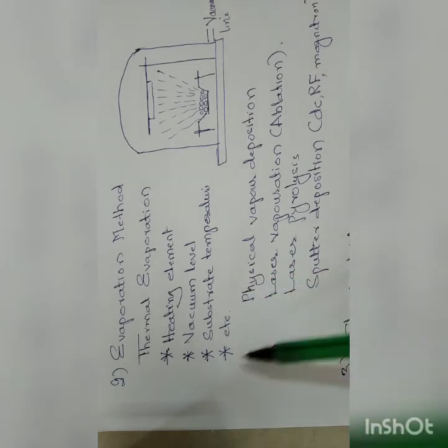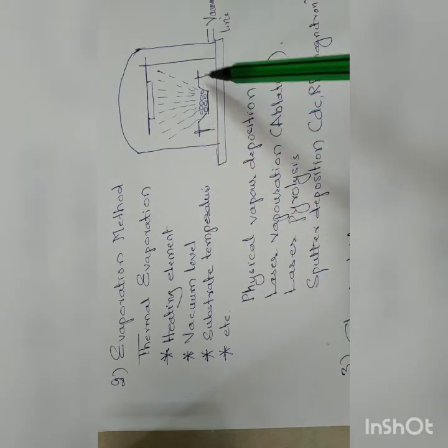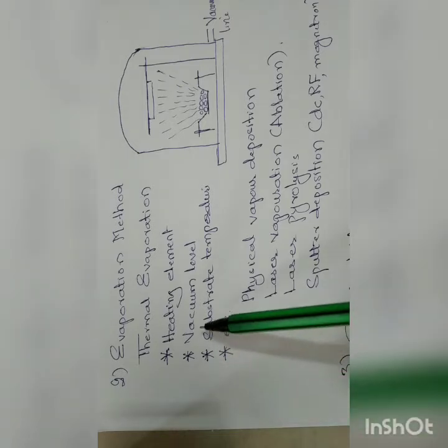Well, there are various critical parameters in such synthesis. I have just quoted heating elements. What you use as a heating element should be non-reactive, but at the same time it should be highly conducting so that you can use it as a heating element. The vacuum level in the chamber is also an important parameter, because at low vacuum there is a possibility of oxidation, while at high vacuum you can have a purer material.